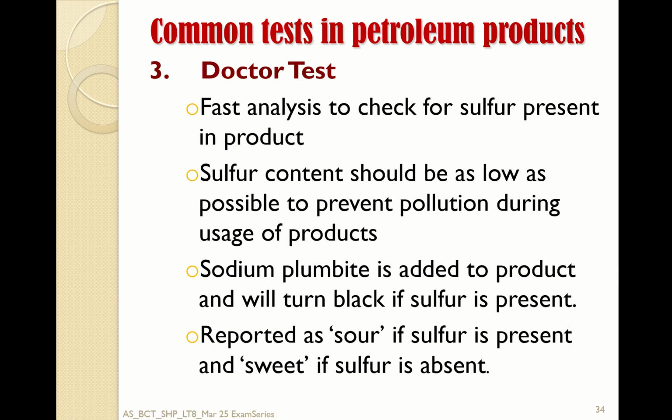The doctor test is not where you go to the doctor and get an MC. Remember just now the sulfur content, sweet and sour? This one is to quickly tell you whether there's sulfur inside or not. You add this chemical, sodium plumbite, so there's lead inside here. When there is sulfur, it will react with the lead and become black in color. If it's black, it means sulfur is present, and it's reported as sour. If it's absent, there's no change in color. That is called sweet.